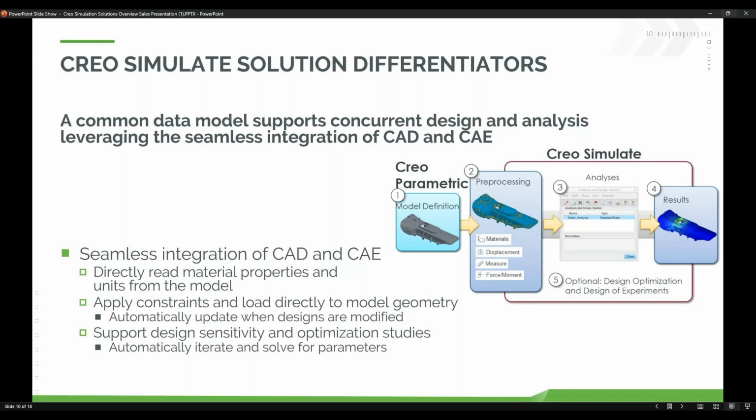So we can use sensitivity studies to go in and determine which dimensions or parameters are important in the analysis. And then when we run our optimization study, we only include the dimensions that are going to be important to our study. There's no need for me to put in the width of the diving board if it has minimal effect on the deflection. That's just more parameters, more meshing, more runtime, more computer time.